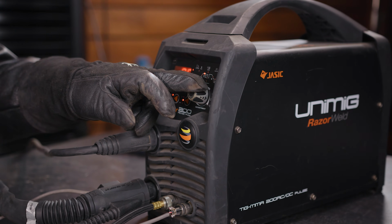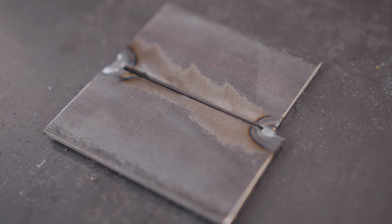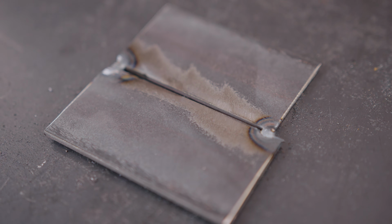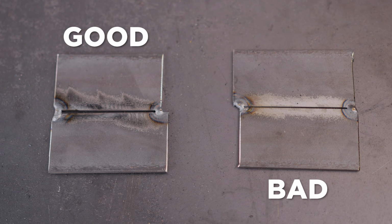Check that you're using appropriate amps, volts, wire speed and traveling at a speed to match. Make sure that you're holding your torch at an appropriate angle with a tight arc. Prep your root gap so that it is not too narrow that you can't get into it, but not so wide that you can't fill it and you burn through.